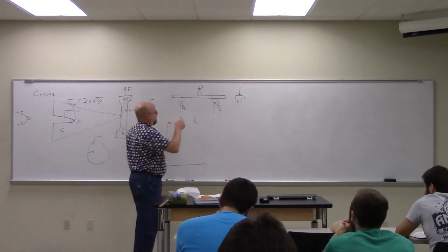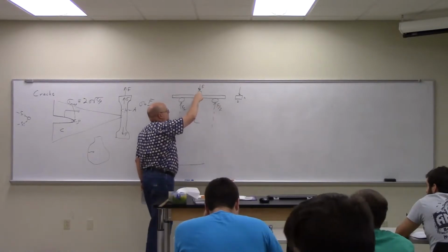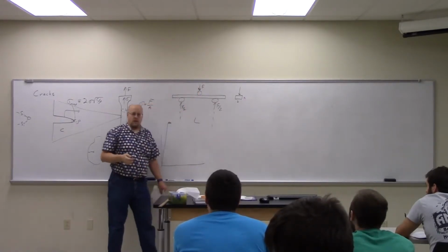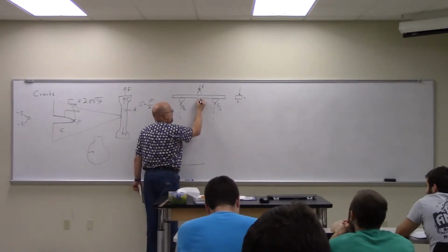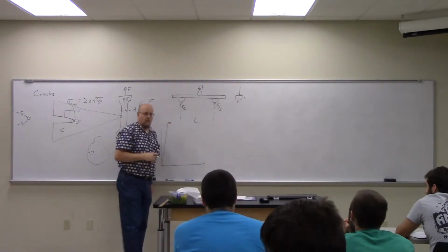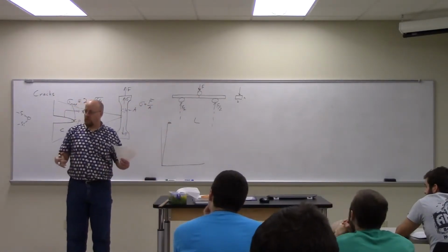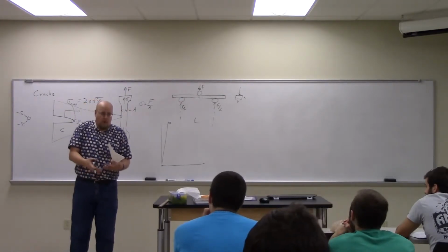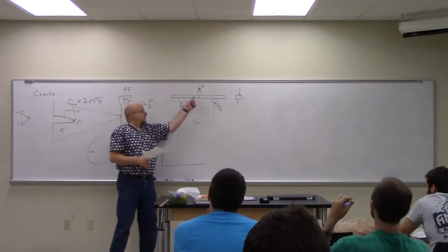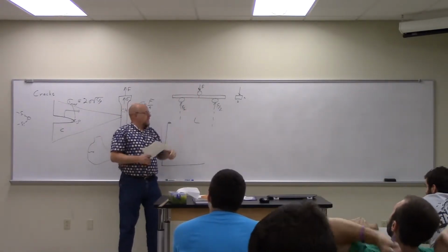So with a ceramic material, since we can't really tensile test it very effectively, we apply this force and wait for it to break. Because what's going to happen is somewhere along the line I'm going to get a crack to grow here and it's going to go right through there. I'm going to start on the bottom surface where I have the most tensile stress. You can kind of see that I'm bending it so that I'm pulling the bottom part apart, while at the same time I squeeze the top together. And so I'm going to get a crack that grows from the bottom.